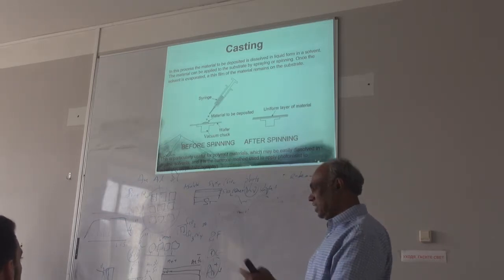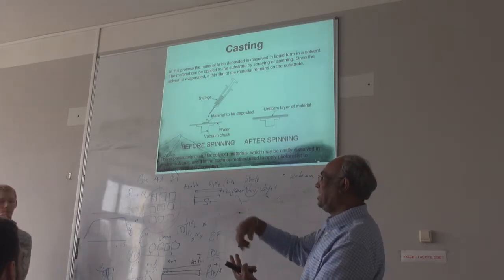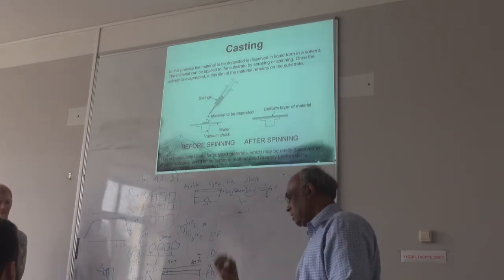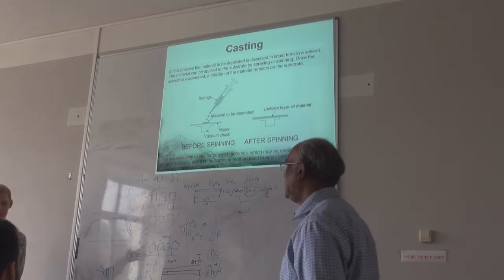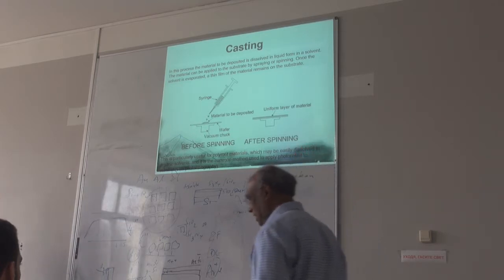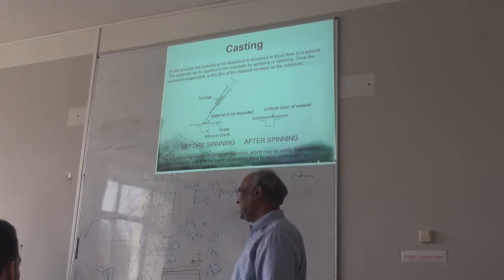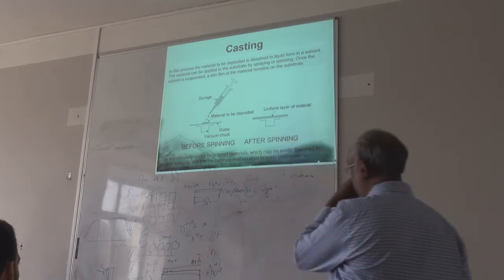A spin coater is simply a motor, your wafer, and some vacuum to hold it. We used a fan from a computer. Otherwise, they can be very expensive. You can make a spin coater for like $2.